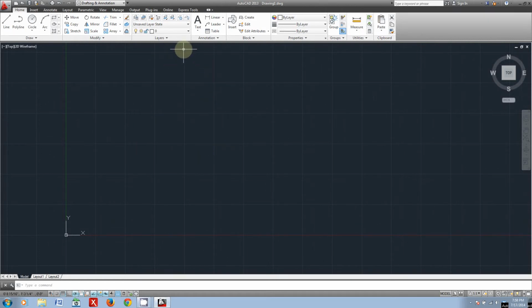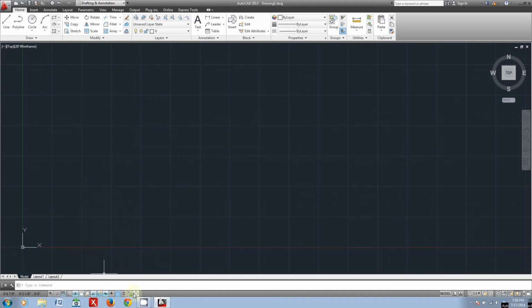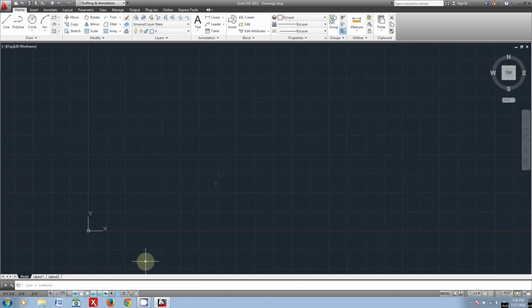It's very useful. So now a couple extra options. You can select whatever you want. I like to have the grid on. I also like to have polar tracking on. As for object snap, I like to include endpoints, midpoints, intersections, tangents, center points. You can do whatever you really feel like, but these are all kind of just personal preference stuff. And I also like to include dynamic input. That just makes it much easier if you want to draw a line, say, at a particular angle. Then you can directly input, say, 45 degrees, and then change the line to whatever length you want.